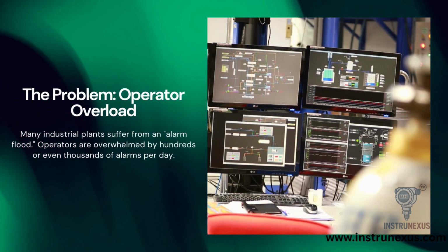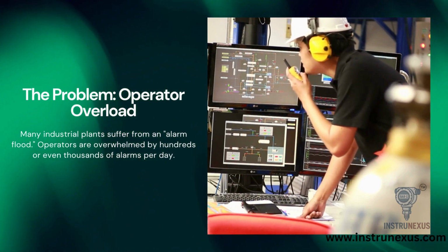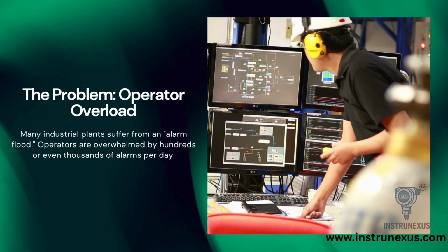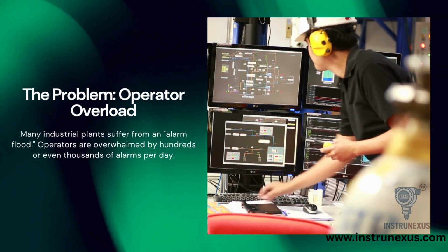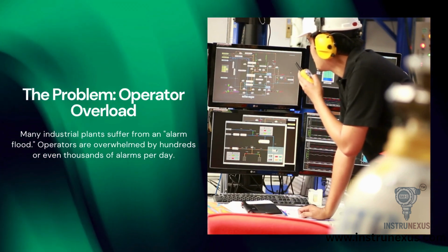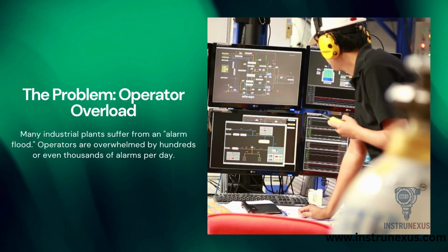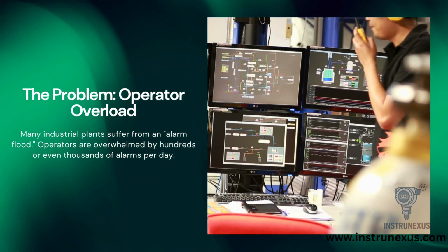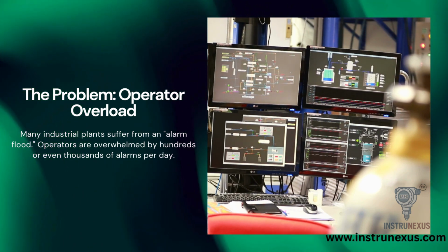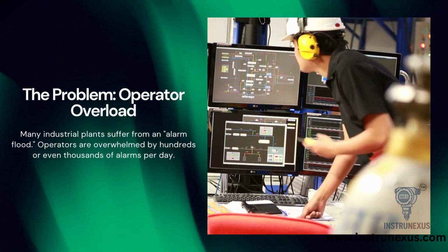Why do we need a standard? Because we have a massive problem in the industry called operator overload. Many industrial plants suffer from what we call an alarm flood. Imagine trying to drive a car while your dashboard screams at you about the radio volume, the tire pressure, the wiper fluid, and the engine temperature all at once. That is the reality for many operators who are overwhelmed by hundreds or even thousands of alarms per day.